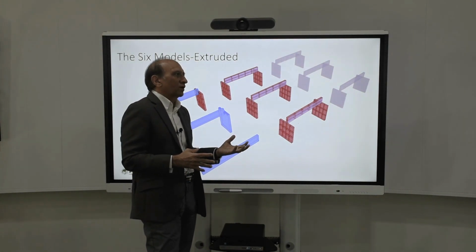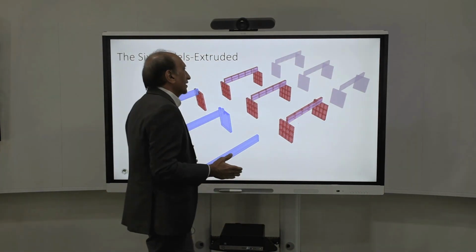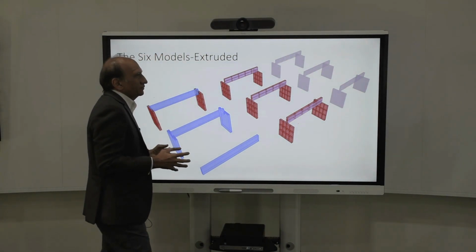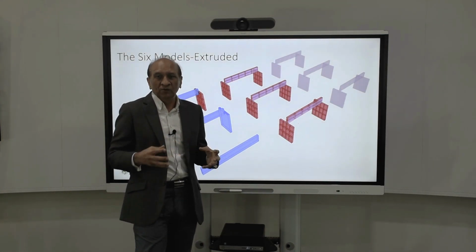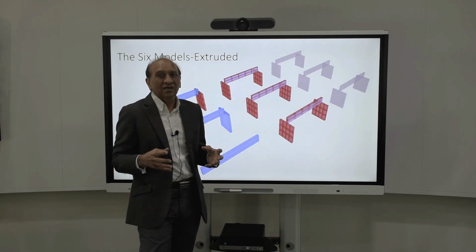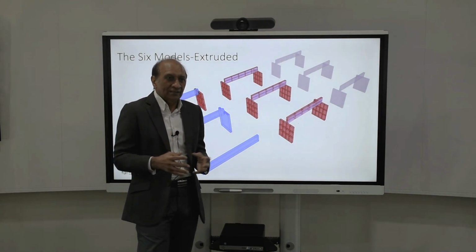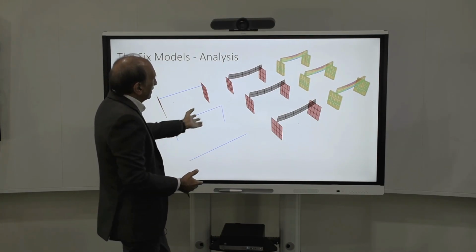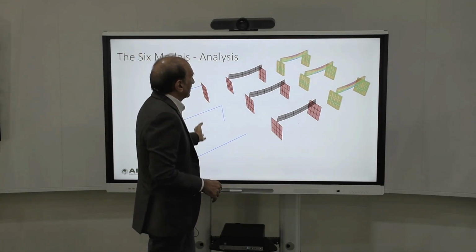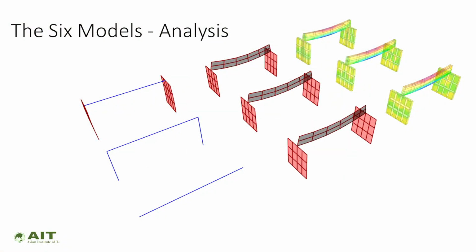And we started with a very simple problem of a beam on 2 walls. What can be simpler than that? So what we have learned so far is that even with that simple problem, it is very, very hard to model everything as we want, unless it's a master thesis, in which we are only doing this for 6 months or 1 year. But in a design, we have very little time to do that. So if you just look at the models, they will all have different responses. Some will give you bending moments, some will give you stresses, and you can see solid models of different kinds where we try to solve many problems of the beam going to the end, not going to the end, and so on.